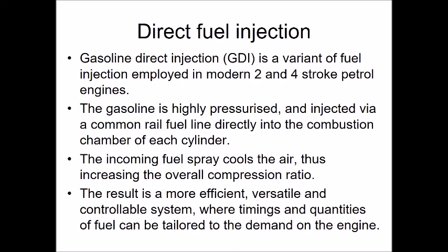So we have this common rail fuel system, so we've got a very high pressure pump driving all of this, and then a valve opens, it's squeezed through a very small orifice, and then we get a spray developed inside the combustion chamber. And if you thought that timing with valve opening and closing was crucial, this will probably blow your mind. It's really quite clever. We have very intelligent computers controlling a lot of this, and they can play tunes on it. So this is all about timing with this one.